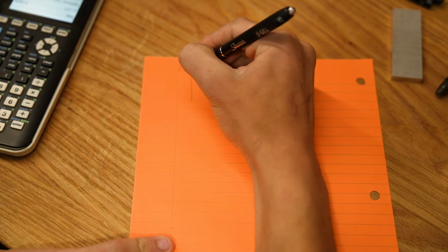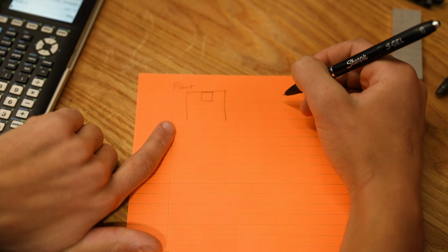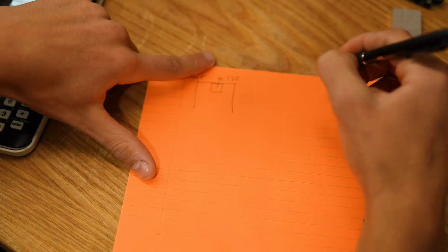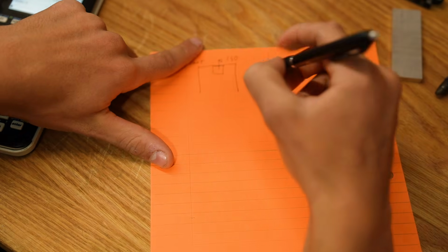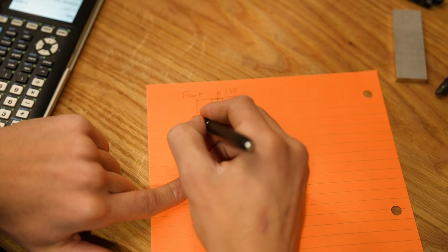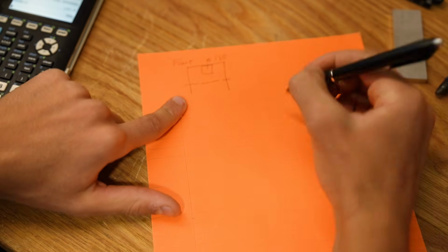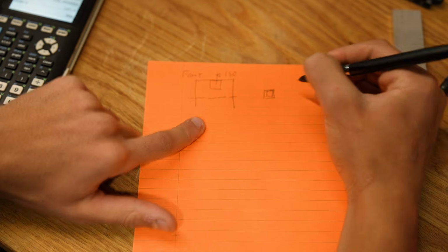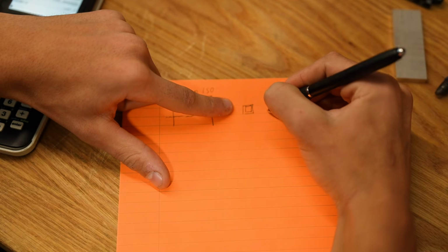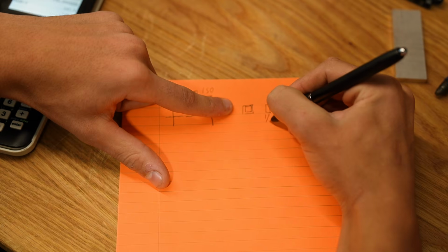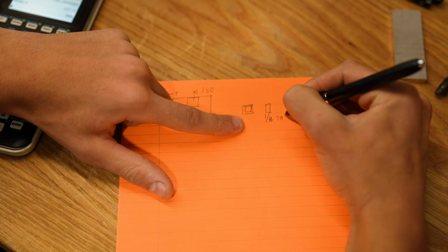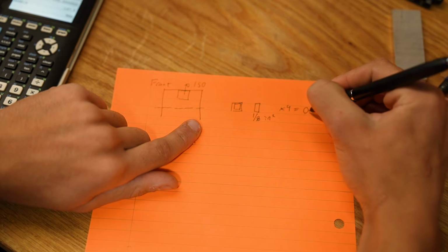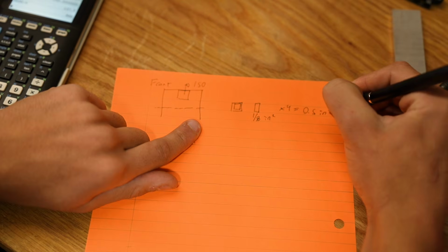Here's a front view of our robot under load. We experience 150 pounds in the vertical direction. That 150 pounds has to be resisted by this cross section of superstructure. We know that we have 4 members in that cross section. Each is a 1/16 inch wall piece of aluminum box tubing. Each one has an area of 1/8 of a square inch, resulting in a total cross section across all 4 of 0.5 square inches.